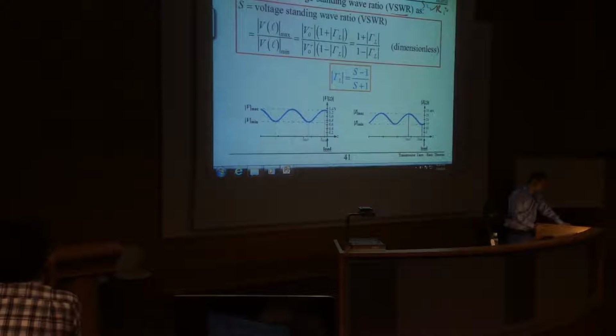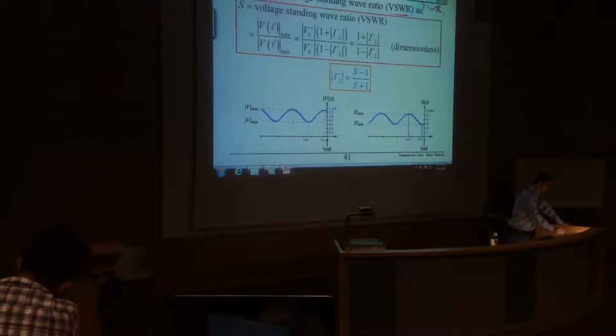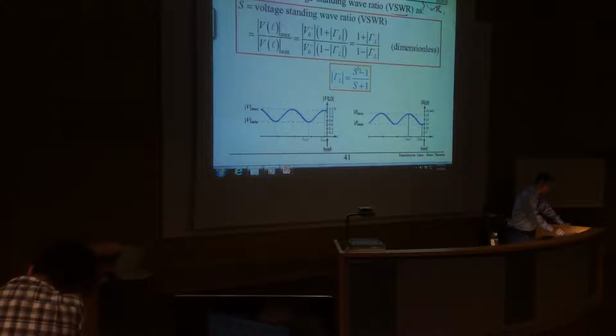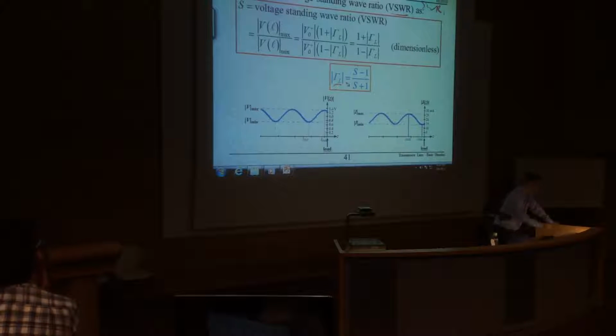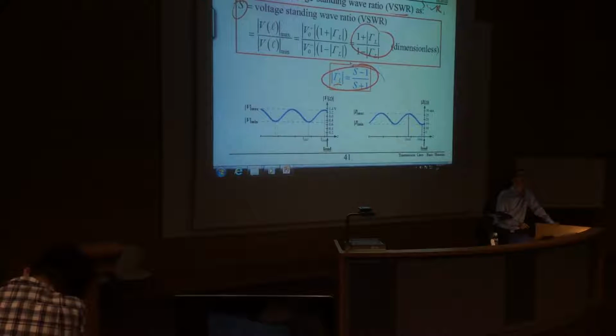The relationship between SWR and the reflection coefficient gamma: from the standing wave ratio, you can calculate the magnitude of the reflection coefficient. These two equations are very important.